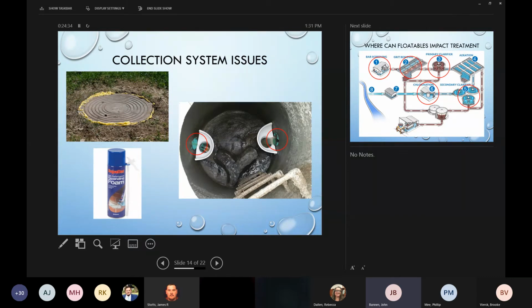And then the same thing happens as the groundwater surrounds those manhole columns or areas. That groundwater will actually push that insulation out of the joints or out from around the pipe, and then pushes it into the manholes, becoming a problem and debris in the collection system.